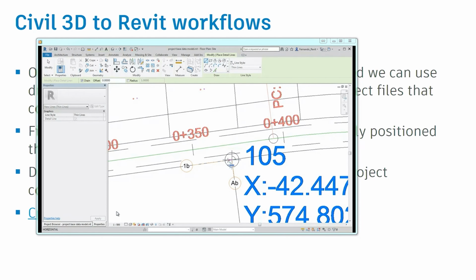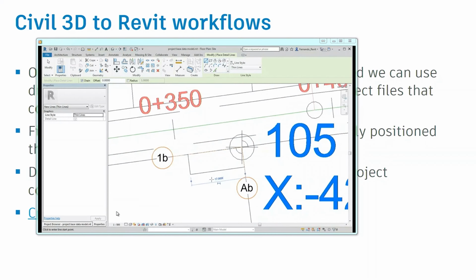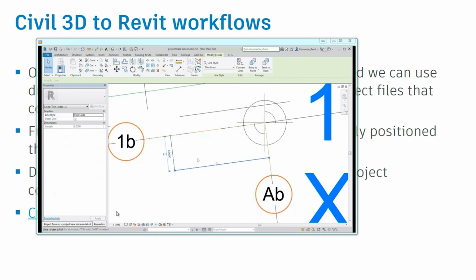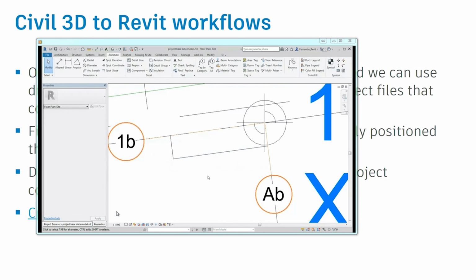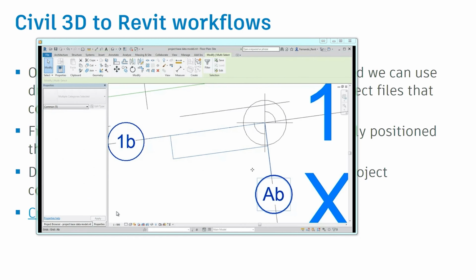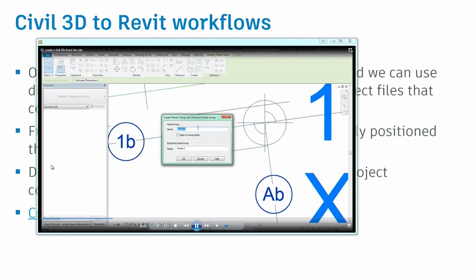Who are Revit users here? They know what to do? I hope so. Well, we're going to select that object, create a group, and generate a link file. And apply the coordinates to that link file. And that file, I give it to my colleague, who continues to work on a base file that correctly lands in my project in the future. That's one of the solutions we had to keep consistency and connection.